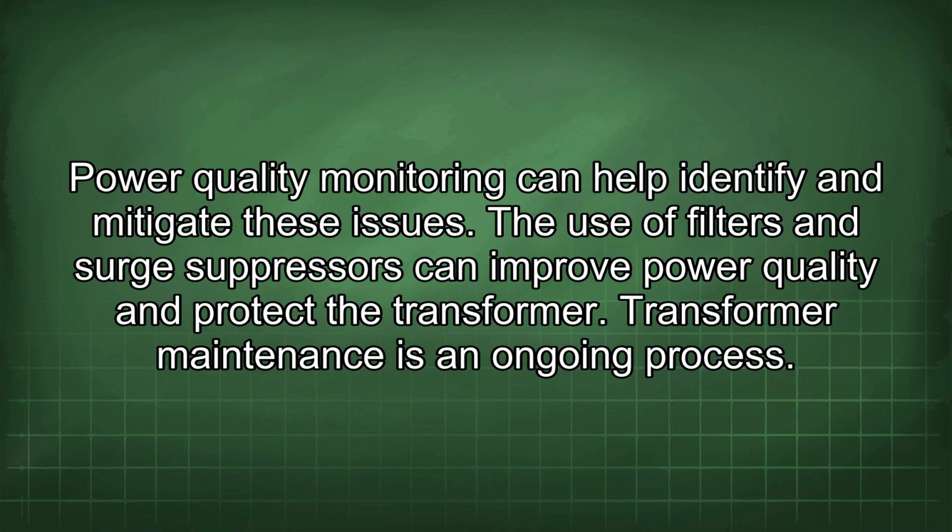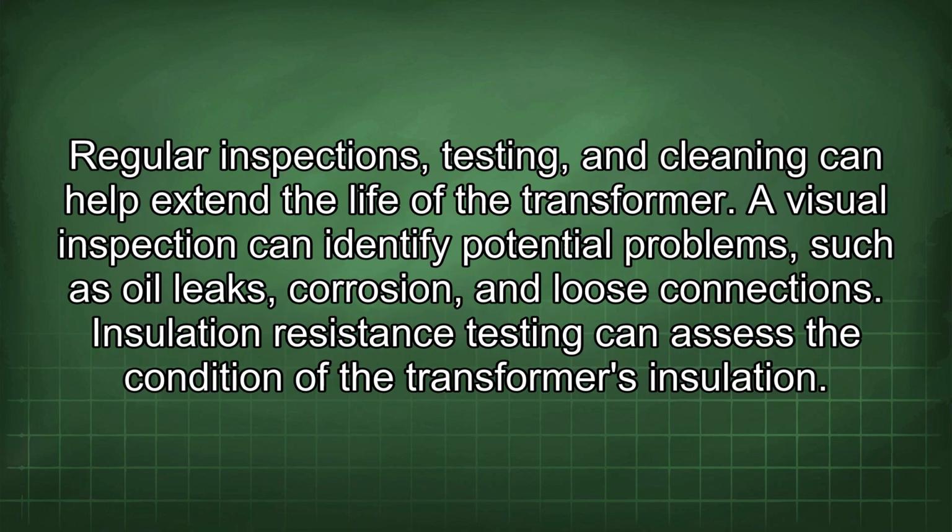Transformer maintenance is an ongoing process. Regular inspections, testing, and cleaning can help extend the life of the transformer. A visual inspection can identify potential problems, such as oil leaks, corrosion, and loose connections. Insulation resistance testing can assess the condition of the transformer's insulation.